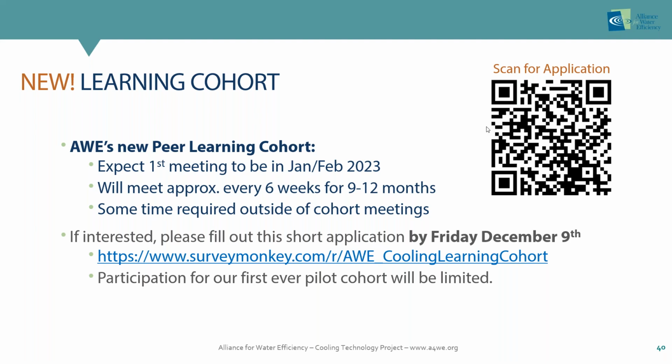Well, on the results tab of CTEM, it will show you what the consumptive use and non-consumptive use is, where the non-consumptive is your opportunity unless you're offsetting the consumptive makeup water with an alternative source. So it has the total water use, and it gives you the ability to adjust the cycles of concentration at a high scale level.